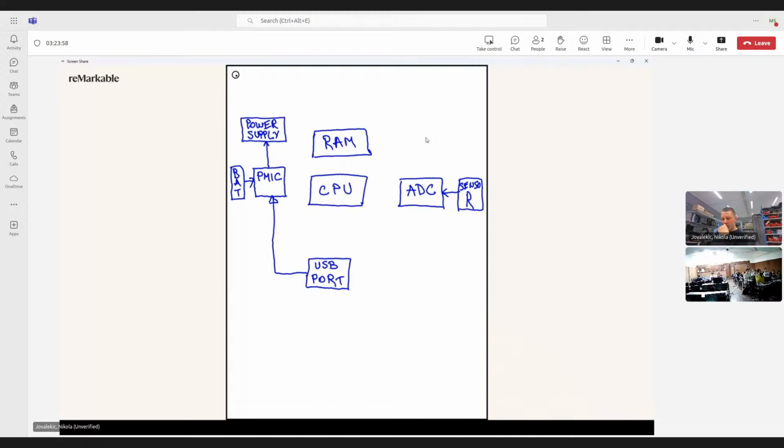Sorry, you said you would first do the power supply part. Yes. Okay. Yes, so I will just tell you how I think. Maybe it will help you. When I'm thinking about design, of course, I firstly tackle the power supply scheme, the power supply tree, how I provide the power supply. Once I resolve that part, so that I can deliver clean power supply, then I tackle other things, how to connect. Of course, when I do this, I have the whole picture in my head. That's also important. Otherwise, you cannot do this part. But okay, this is also a valid and good approach. You start from the inside out, let's say. It can also be tackled in that way. There is no problem with that. Not at all. It is actually a matter of personal preference, nothing special.